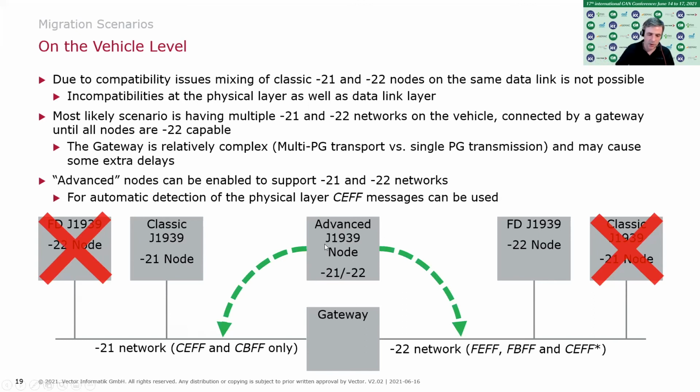Of course you need to pick a CAN FD capable CAN controller, as well as a transceiver chip which supports the 2 megabits. And then you can create such a node that can, by software, distinguish if it is connected to a classical or a FD data link, and it can work on both sides.